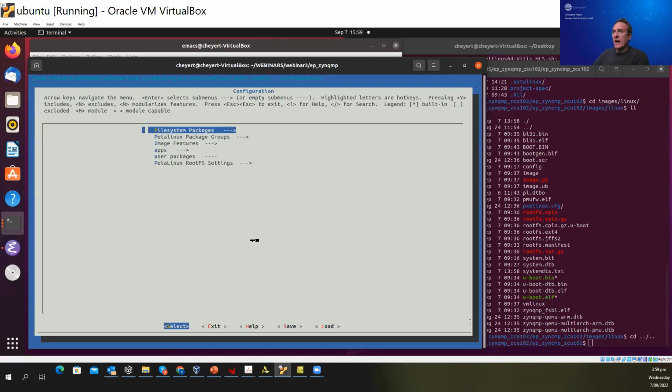But obviously we can also add packages. You can customize your root file system as per your preferences. So what I would like to add, for instance, here is, because we've added an Ethernet MAC, so we are going to see Ethernet up and running in a few minutes. I want to, for instance, add enable ETH tool, or TCP dump. So obviously you find a lot of packages, so whatever you wish to add.